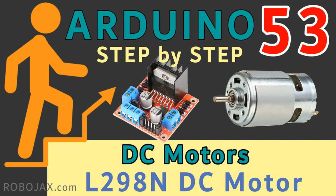Operation: Bipolar drivers reverse the current in the motor's windings to generate the magnetic field, allowing for a higher torque output. Advantages: higher torque than unipolar drivers, more efficient use of the motor windings. Disadvantages: requires more complex circuitry and can generate more heat due to the full use of the windings. Applications: common in high-torque applications, such as CNC machines, robotics, and 3D printers.